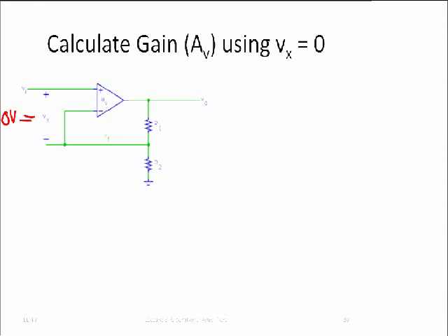If you put a voltage source in between there, then of course the voltage is pinned by that voltage source. No longer can the operational amplifier and the feedback loop say, I'm going to set this voltage such that the difference Vx is 0, right? So don't put a voltage source there.